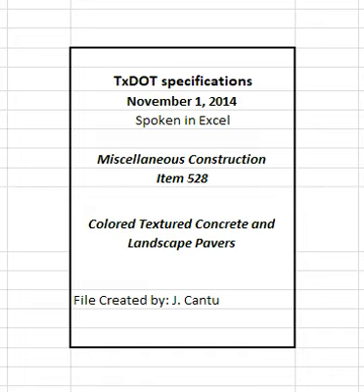2.2.3 Joint filling sand. Meet the requirements for bedding sand, except with the gradation given in Table 2. Table 2. Joint filling sand gradation. Sieve size and percent passing. Sieve size number 4 with 100% passing. Sieve size number 8 with 90 to 100% passing.